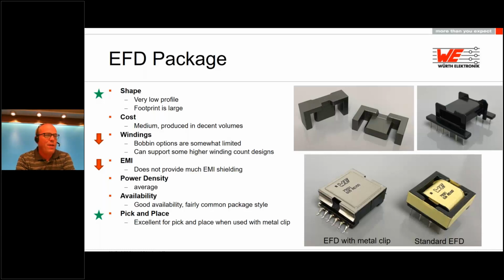There are a few common EFD sizes. I'd say EFD 15, 20, 25, and 30, but there have also been a lot of custom EFD style packages developed for specific industries. So while I say that there isn't a wide variety of standard bobbins available, it seems to be one that's popular to use as a jumping off point for a lot of custom designs. So definitely one to consider. If you need low profile, this is probably the one you'd start with.